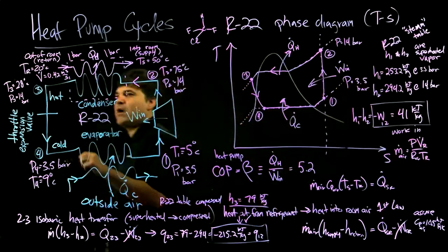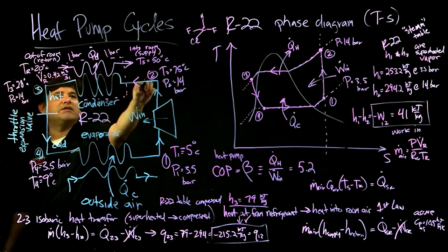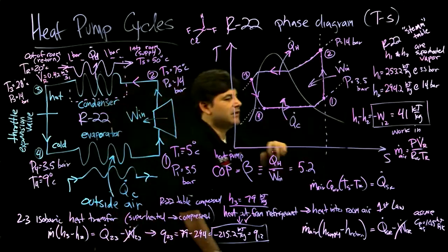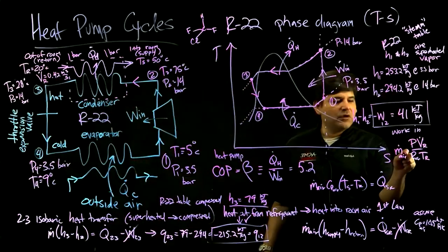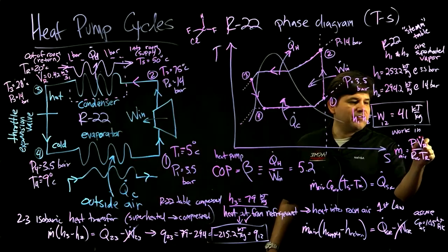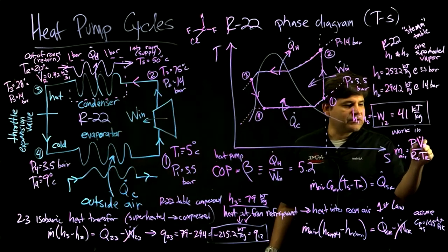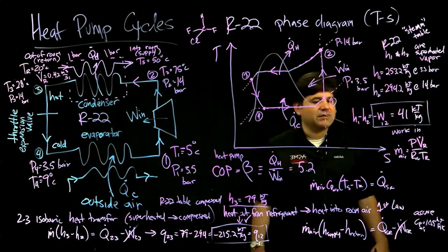So this is specified for the return side. Because of different temperatures, the volumetric flow rate is going to change according to the ideal gas law. So we can focus on a steady flow. The mass in equals the mass out. And as long as you're using the volumetric flow rate and the temperatures corresponding to each other, you should be able to get the mass flow rate.